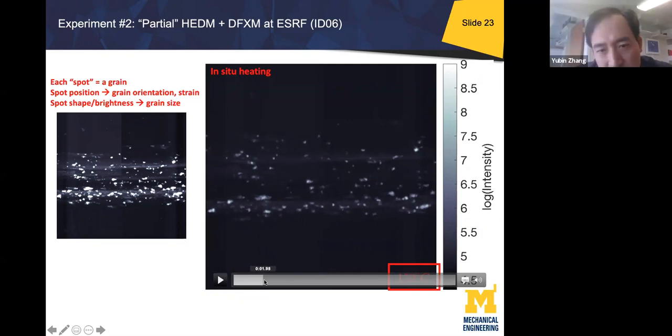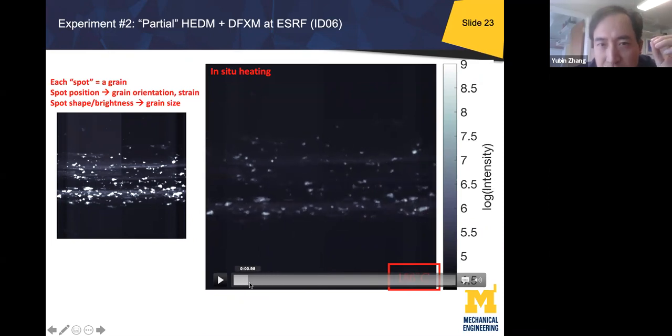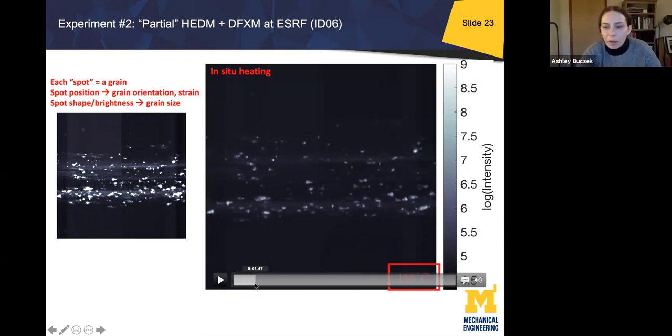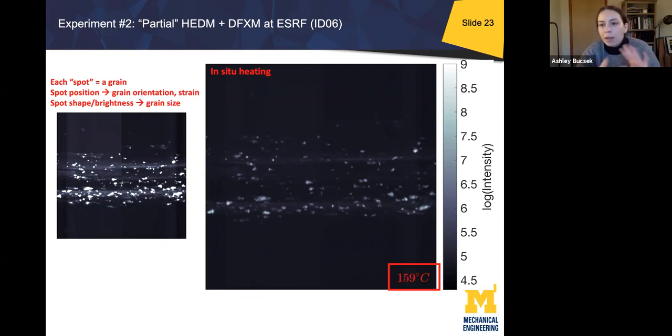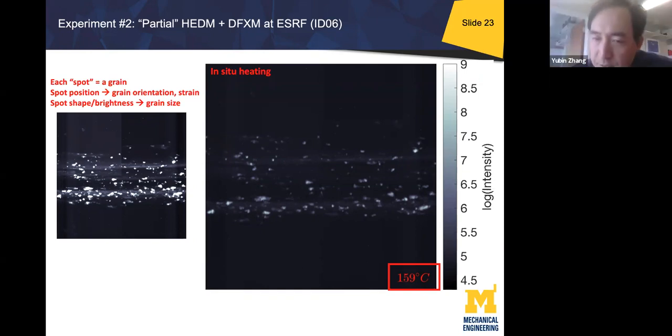So that means when the grain is recrystallized, when they absorb the dislocations, they change their orientations too? Yeah, I think so. In the recovery process, the dislocations are annihilating, and maybe there's some average change to the orientation. The grains are rotating a bit, and I think Sonia showed that too in her Acta Materialia paper with Henning and Hugh as well. These grains are really active, and the subgrains are really active even before you really get into these annealing processes. Yeah, thank you. That's very interesting.